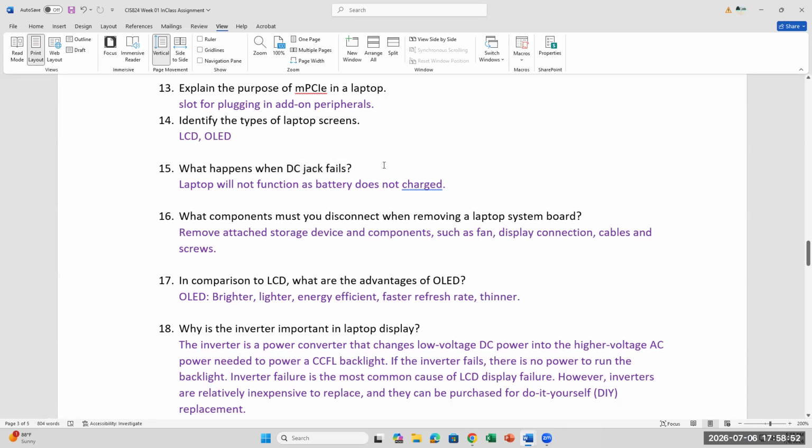But when the battery on your laptop is swollen, it's because you overcharge. If you have a swollen battery, you can tell when you set it on a flat surface, it wiggles, right? You move it, it swivels. It happens a lot on Chromebooks. I know this, right? The rule is that they're going to sell you components that are half charged. On the new battery, the cycle is not remembered.